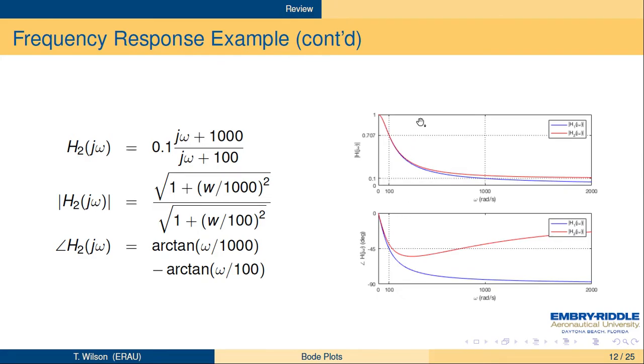Well, it looks a lot like the first curve for very low frequencies. It's hard to tell them apart. I mean, in the magnitude curve, you don't see any difference between the two curves. It's only as you go to larger frequencies that you see the first filter with just the RC continue to roll off, whereas, as we said, the high frequency gain of the second circuit ought to be 0.1, and you can see it approaching 0.1 asymptotically there.